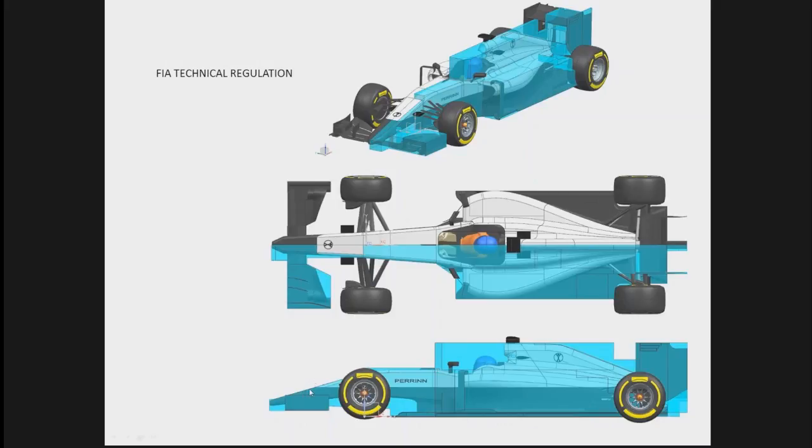The problem with the short nose is for the crash test, obviously the distance, there's so much energy that you need to absorb from the nose in the crash test. Having a long nose is a much easier way to do it for the crash, and it will be lighter because you won't have to build the nose with so much thickness into it for the crash test. So the short nose is difficult to achieve.